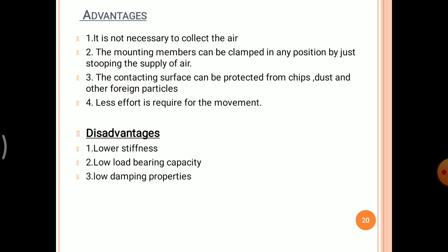The contacting surface can be protected from chips, dust, and other foreign particles. As we are making use of compressed air, these particles will be completely kept out. That is, chips, dust, and other foreign particles will not stick between the moving surface and fixed surface. Less effort is required for the movement. So these are the advantages of aerostatic guideways.